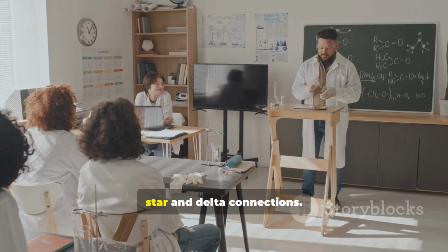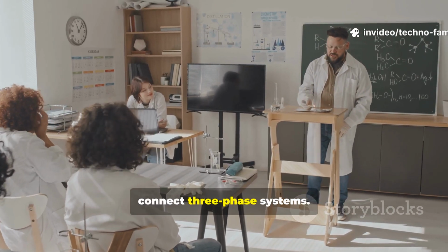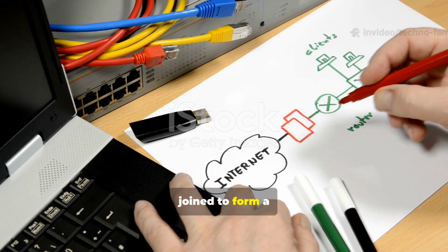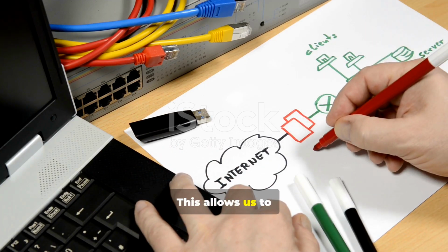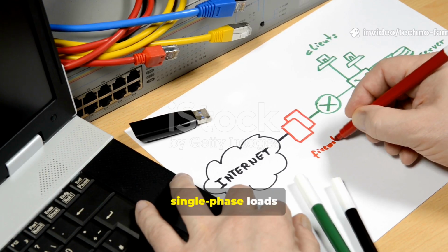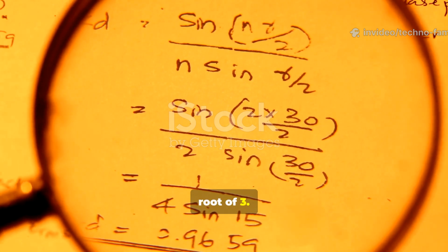Now let's move to star and delta connections. These are the two most common ways to connect three-phase systems. Star-Y connection. Here, one end of each phase winding is joined to form a neutral point. This allows us to connect both line and neutral wires, which is useful for supplying single-phase loads as well. The relationship is VPH equals VL divided by square root of 3.